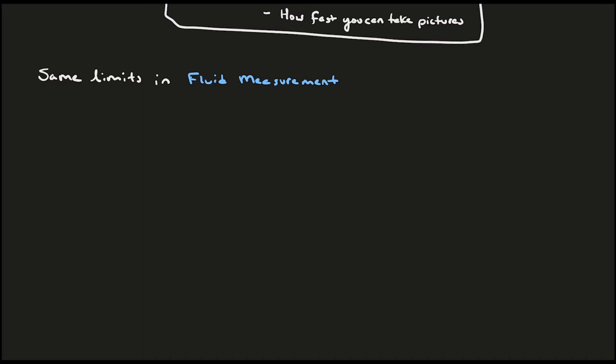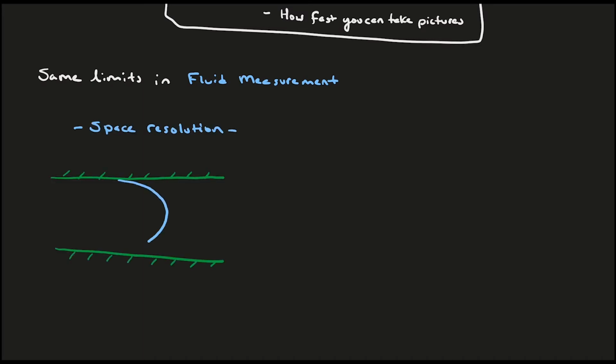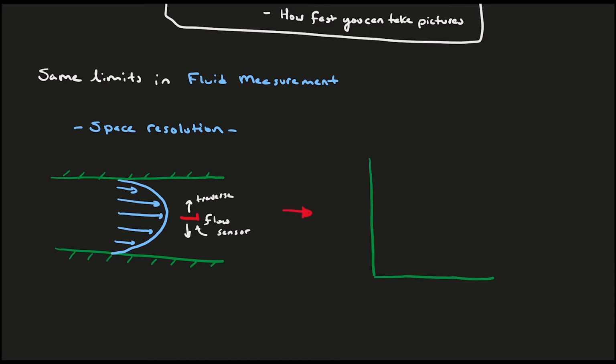Consider our laminar channel flow and the resulting flow field. In this flow field, we've placed a flow sensor that can traverse in the y direction. On the right, let's plot the velocity against the vertical location, also known as the velocity profile. First, we know the real profile is a parabola, the solution of the conservation equations we came to in previous lectures. Data points from this sensor fall on top of the real profile, however the points have a fixed spacing at a certain distance apart.